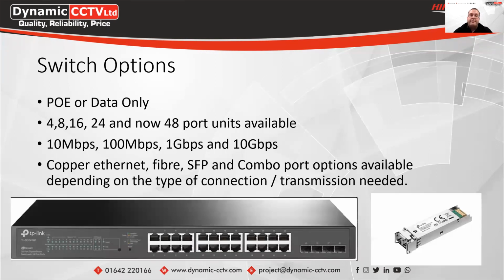So with switches, there are a few different options. You've got PoE switches, which allows you to provide power over Ethernet, and this is generally how you would power IP cameras. Or you can have data-only switches, which will only transmit data from them. And generally, you only ever used to see 4, 8, 16 and 24 port switches, but now you can get larger units which can have 48 ports that are available on a single switch.